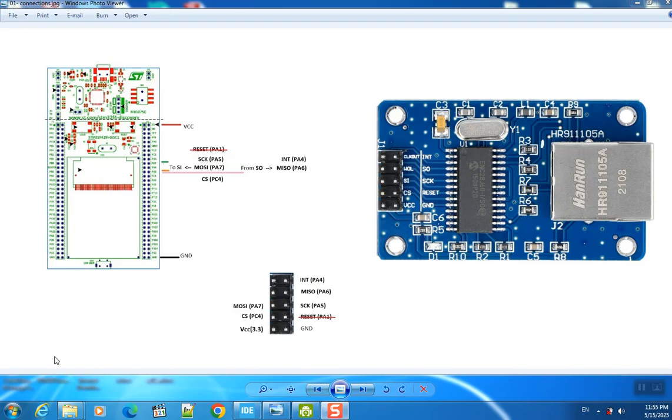For the wiring, I can connect the ENC28 to my MCU, the STM32 Discovery board, like AbouHashem's video. We can make this connection, but note that there is no need for the reset line, so I remove the reset lines. And reset lines are removed here.